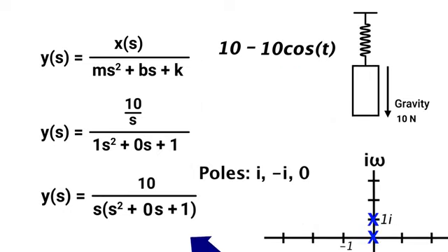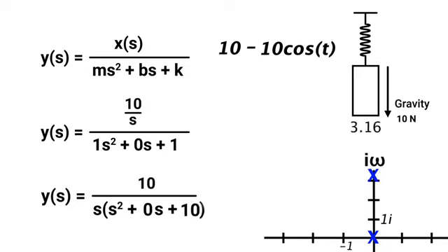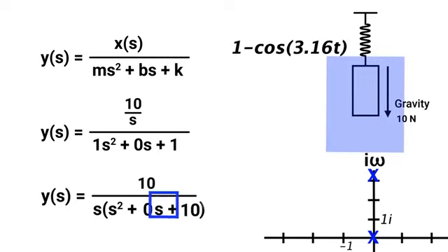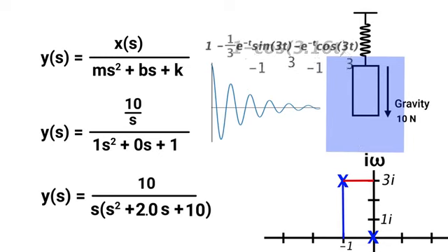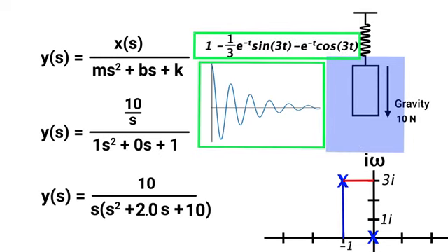If I increase the value of k or make the spring stronger, then the poles start to separate more and more, which represents faster oscillations about equilibrium. If I were to add some damping now or increase b, then we expect slow exponential decay. I'll just stop here at b equals 2 for example, so we can see there's now a sinusoidal and exponential component to our equation, which matches what was expected, even though I'm not graphing the exact output.